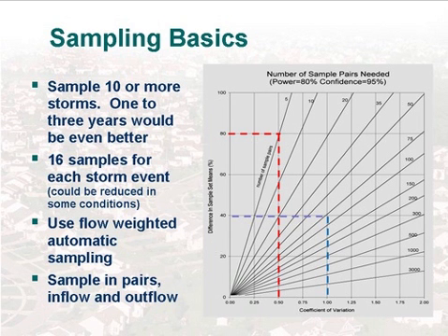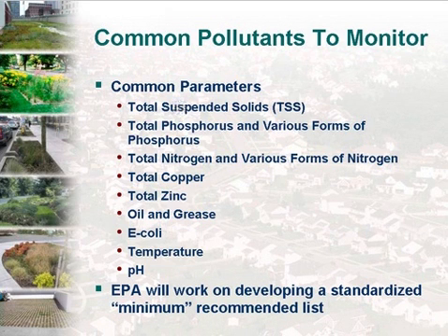We're talking about the storm event-specific monitoring requirements, but throughout your monitoring program, you should be sampling a range of storm events. So you're not just characterizing your concentrations at the smaller storm events, or just frequently monitoring the larger storm events. You want to get the spectrum of your rainfall frequencies. Absolutely, which is why long-term monitoring is even better. If you can monitor for a year or so and really get a good range of storms and events, you'll have a better idea of what's going on in your BMP. And every sample you take is not necessarily a keeper sample. Yes, that's another good point too.